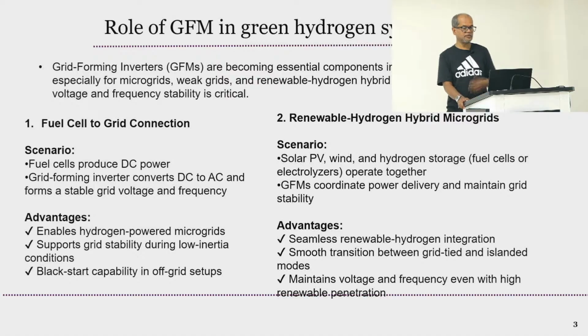But as we mentioned many times, grid forming inverters are becoming essential components for the grid, especially for microgrids, weak grids, and also when you have a renewable hybrid system where you might have hydrogen. In those cases, it is essential that you go for grid forming control for the inverter.